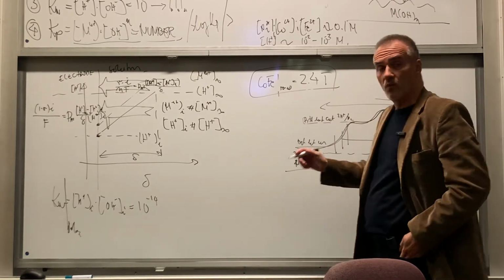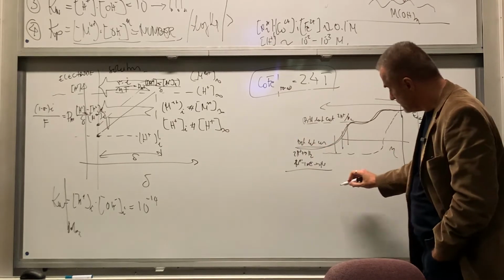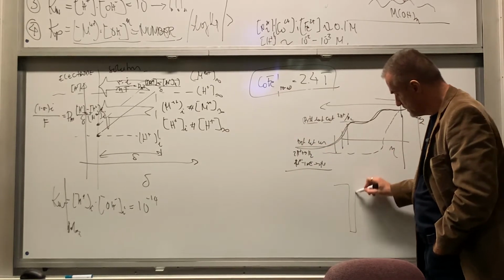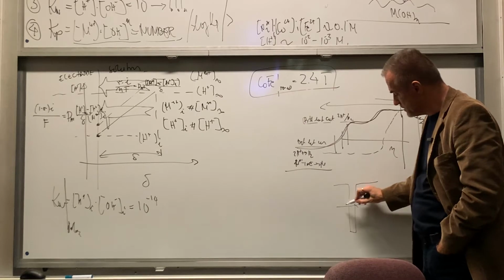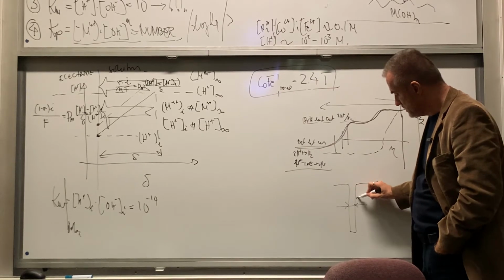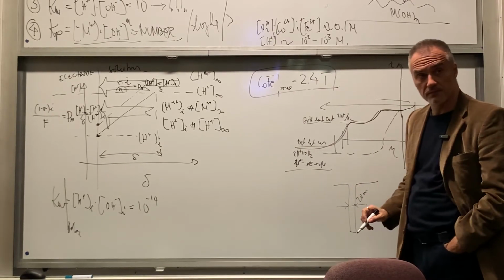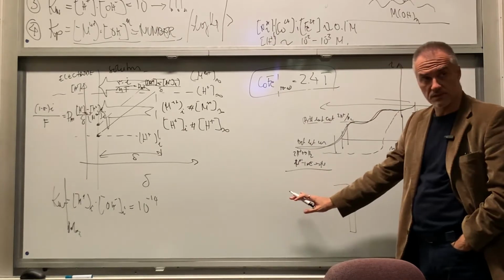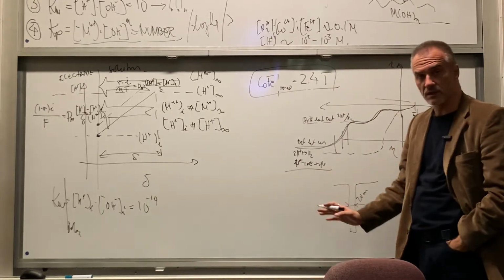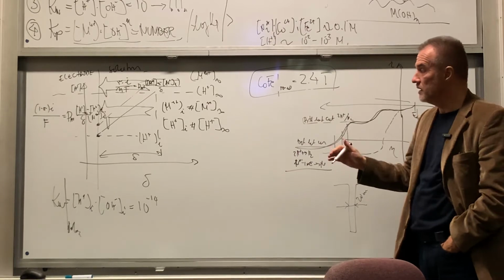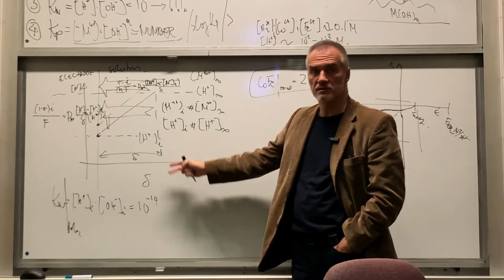Now, when we grow devices, sometimes the resist, this dimension here, is only 20 nanometers. So it's not like open space where you have mixing and you can reduce the diffusion layer thickness and improve the transport and so on.